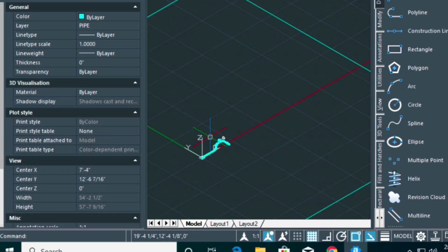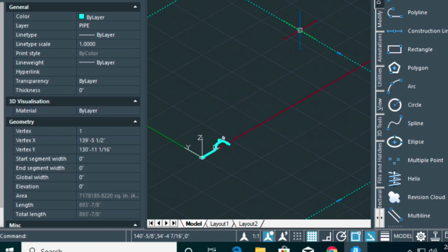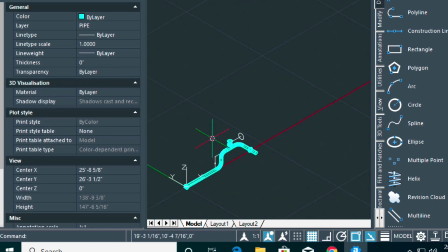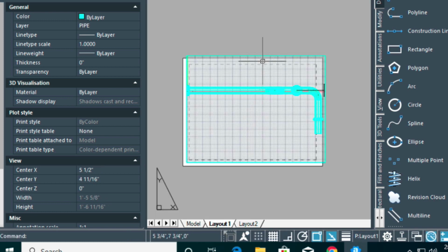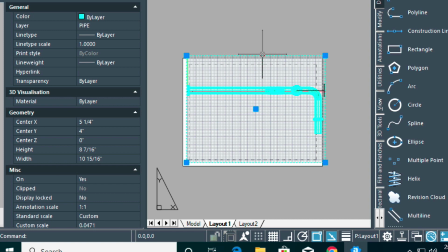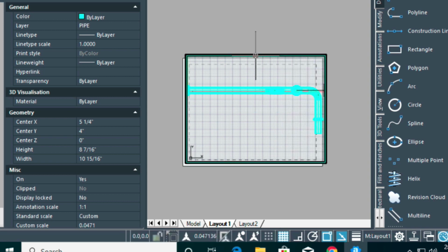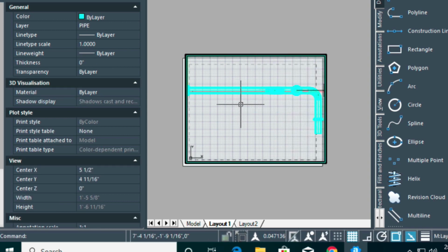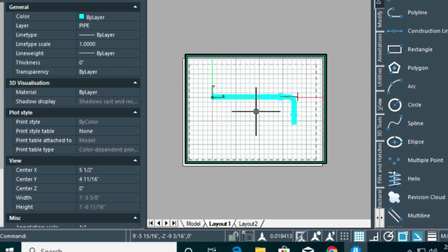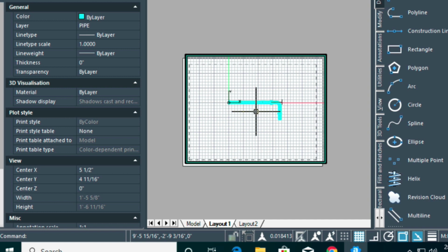Okay. I have a video on this I can reference, but essentially when I click on the layout view, this is that piece of paper that I just showed you, and if I want to view down into model space, I type MS, and that's the hole going down to model space through your paper. We can zoom in and out looking down into model space.